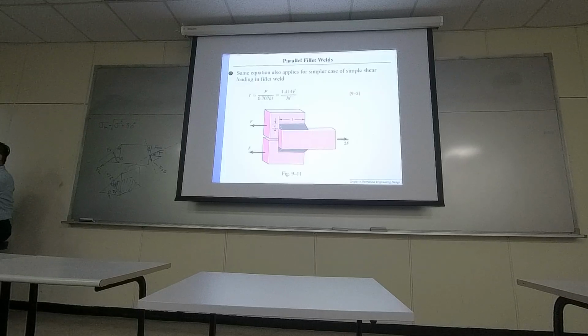So for this particular welding material, the force that contributes to shearing will be F. And the effective stress area is gonna be the cross-section area right at the 45 degree. So 0.7 HL. Okay? That's how you compute the shear stress in the welding material.